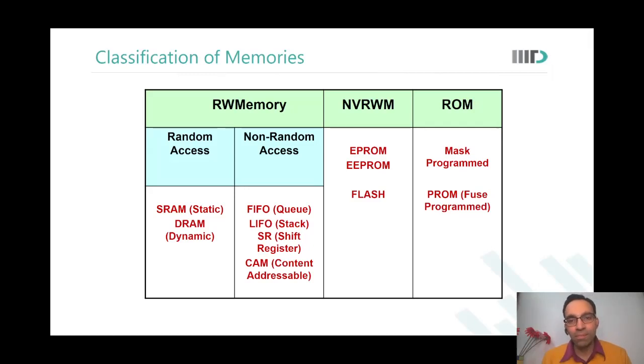Sir, so how is PROM used there, to store the information? Like we need to use it at lower voltages. Yeah. So what I will do is, the voltage regulators on the chip always have some calibration bits. I will make my logic in such a way that the information from the PROM goes and triggers those calibration bits so that this voltage regulator now generates only 1.26 volts instead of 1.3 volts, or 1.14 volts instead of 1.1 volt.